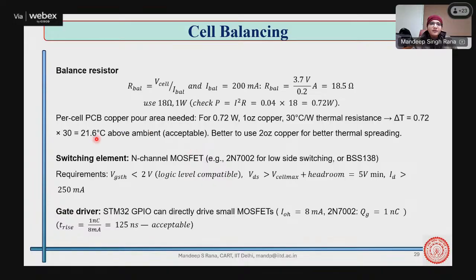But when we consider the temperature difference with the ambience, which is 27 degrees Celsius in general, then we should not go with that much thickness of copper. We should give more copper thickness, which is 2 ounce copper. It means thicker copper layers within the PCB, which can cool faster.